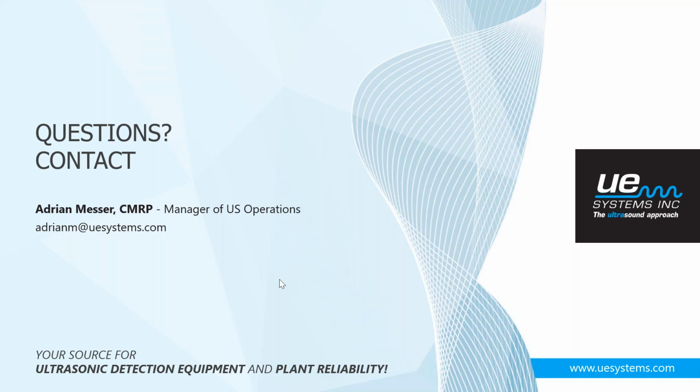Yeah, that's a good question. It's a valid question. So for the UltraProbe 3000, we make a kit specific for leak detection. It's called the UltraProbe 3000 SL kit, which comes with the scanning module. It comes with the long range module, if you do have those overhead airlines, and it also comes with 200 leak tags. It's around $4,200. You pair that with the Leak Survey app, which is free. That's your reporting, and that's what you would need for your leak survey.